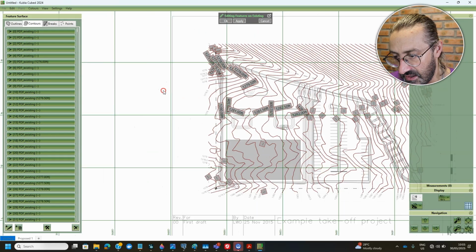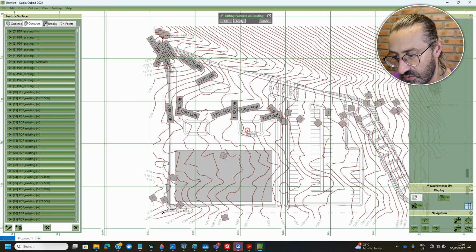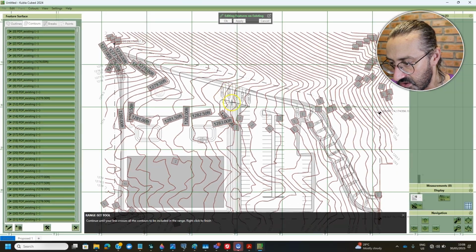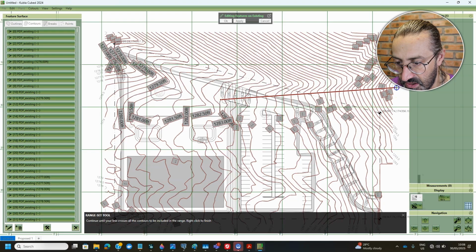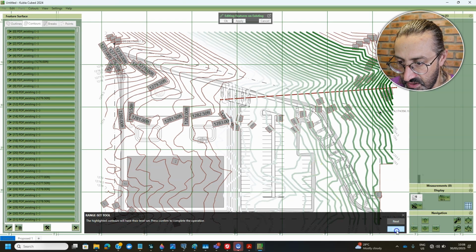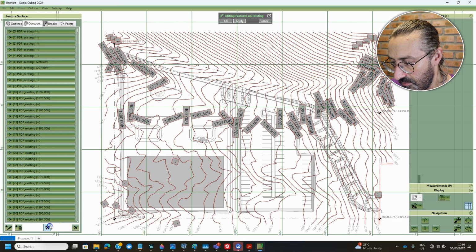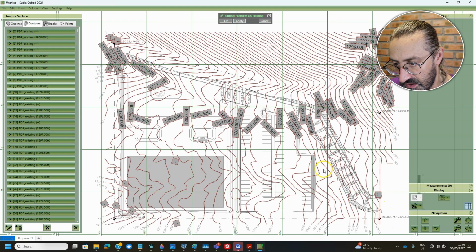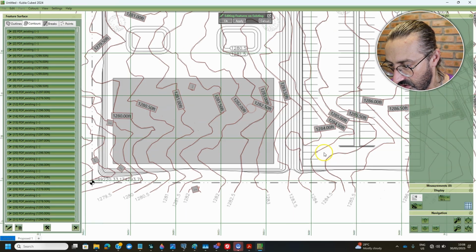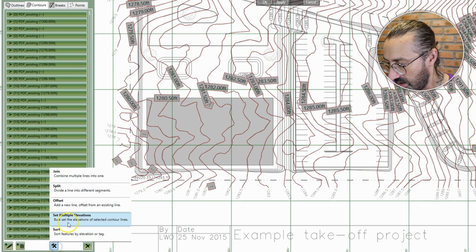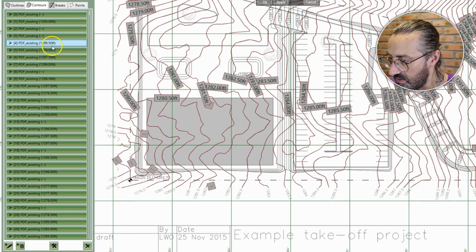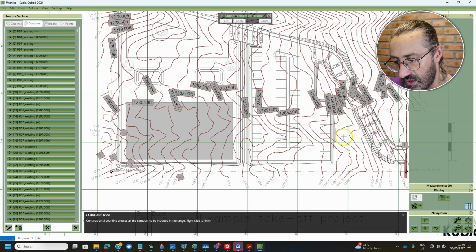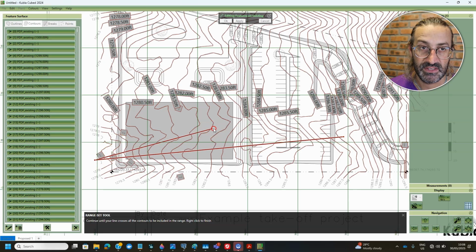Another handy trick is if you sample two that have already been set, it will take that as the starting point. So let's use the tool again, set multiple elevations, and I'll select these two and just continue it along, and it sets all those others based on that first sampling. I'll go up here again, continue, finish. These ones down here have not got selected, so I can do another final line down here. If you see on this list, you can see the ones that are set and the ones that are not set. This is really more of a piece on how to use the set multiple elevations tool.